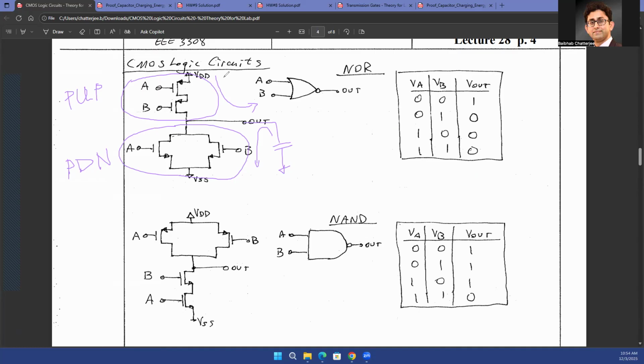On the other hand, why do we use NMOS devices in the pull-down network? That is because NMOS devices are better at being used as a discharging switch, or they are good when you're trying to conduct a digital zero. If you had used a PMOS-based pull-down network, the capacitor would only discharge to the threshold voltage level and not to the zero level. So you may use a PMOS at the bottom or NMOS at the top, but then that circuit will not be efficient. That is the reason why PMOSes are used at the top and NMOSes are used at the bottom of any CMOS circuit.